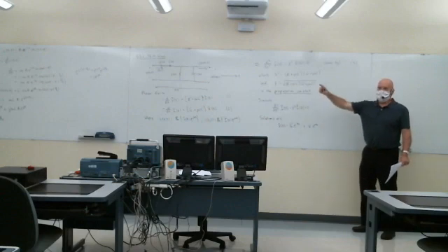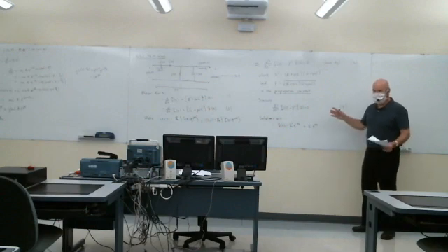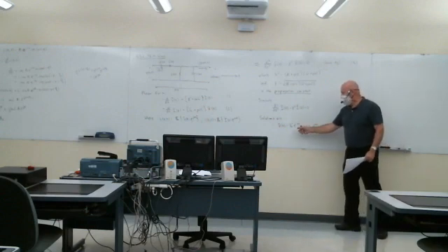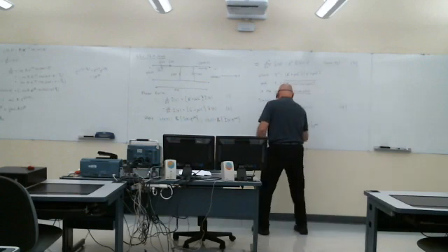It propagates to the wall and comes back. But now I've got both of those waveforms going all the time, so there's interference between those two, and we'll talk a lot about that. This is the portion that's propagating down the transmission line. This is the reflected portion.